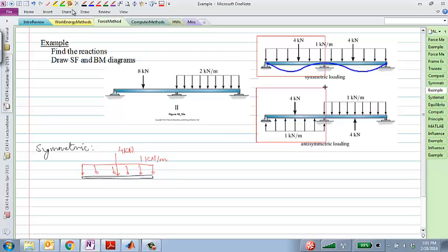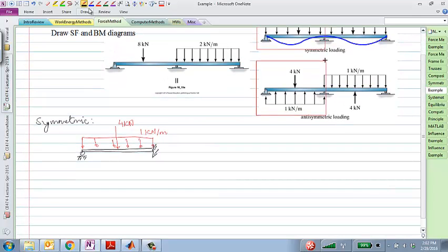And if you look at half of this problem, that's like a fixed support here with a simply supported end at the other end. So we have something like this, and I would break this up into an underlying determinate system.